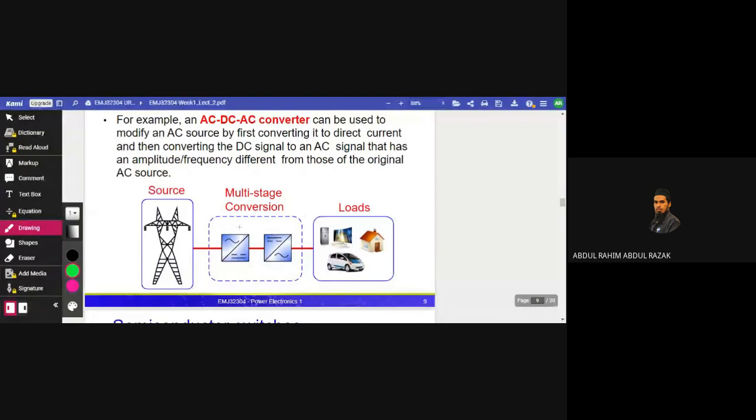Even though at the end we need an AC supply, the AC needed may be at a different level compared to our 50 Hertz incoming, so we have to rectify again. This is the same as the VFD that I showed you before, because the motor itself is AC. The incoming 50 Hertz has to be rectified through the VFD, the variable frequency drive controller.